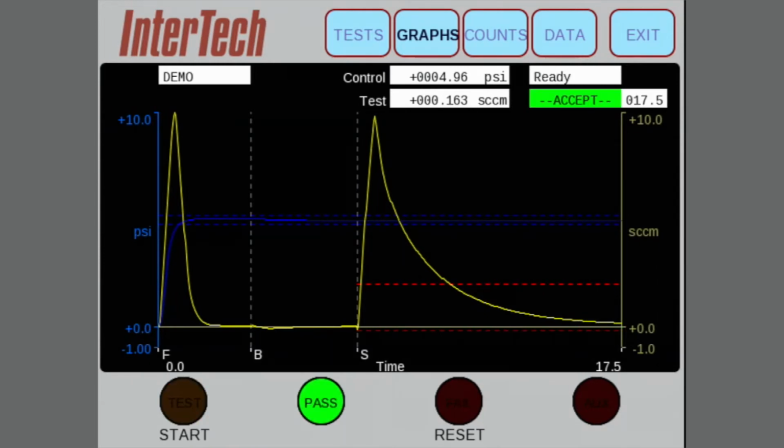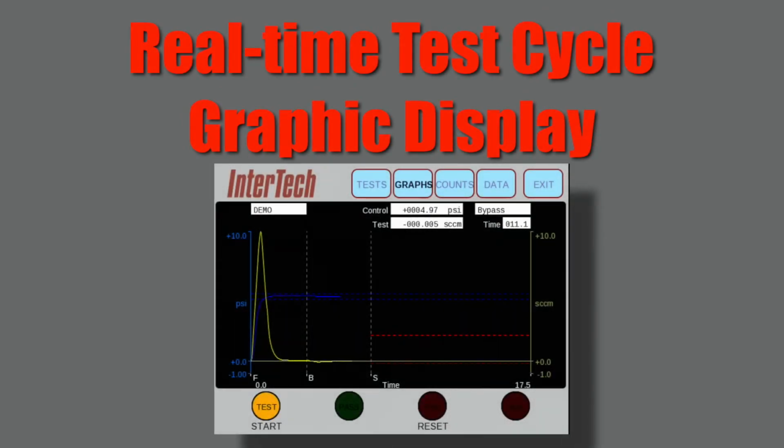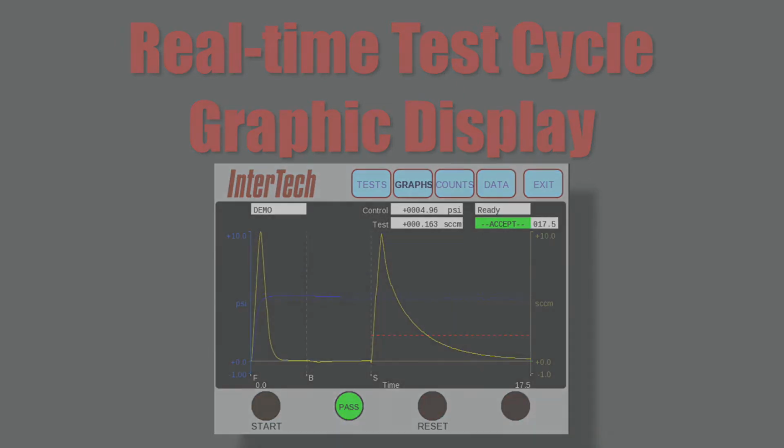The test time required to obtain a leak rate calculation using a pressure decay tester is eliminated. Note the unique operation of the high-speed mass flow test and its corresponding test curve. Eliminating the test time required with pressure decay testing saves the user up to 30% of leak test cycle time.